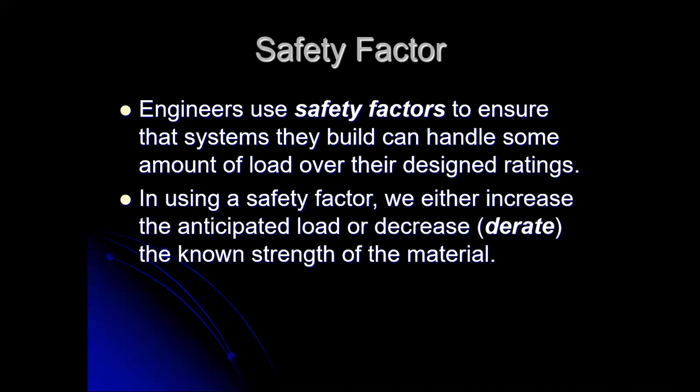So in using a safety factor, we can apply it and integrate it into the system in one of two ways. We can either increase our anticipated load on paper. We know we're going to rate it for 10,000 pounds, but we design it as if it's rated for 15,000 pounds. That would be applying a 50% or a 1.5 safety factor.